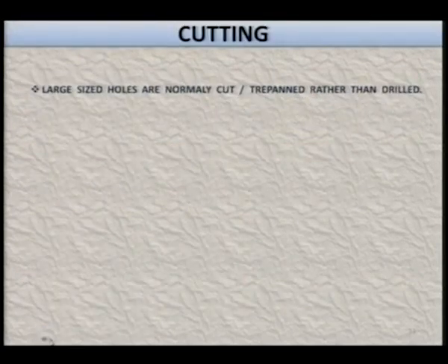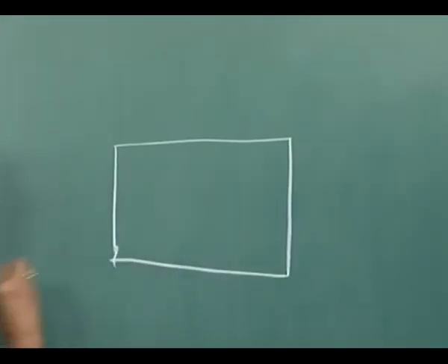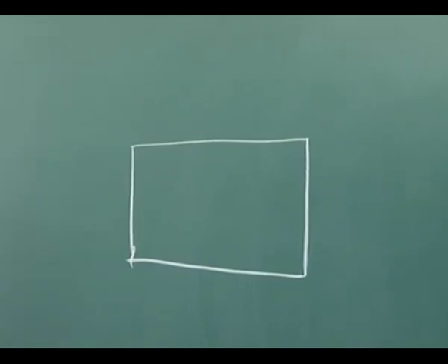Then there are various applications as long as cutting is concerned. Large sized holes are normally cut by trepanning rather than drilling. This is a very important point. I will just explain to you here on the board that suppose this is a workpiece, and if you want to cut or drill a hole of around 1 millimeter, you can do it with the help of the laser beam directly. But suppose you want to drill a hole in a very hard material of around say 15 millimeter diameter like this,